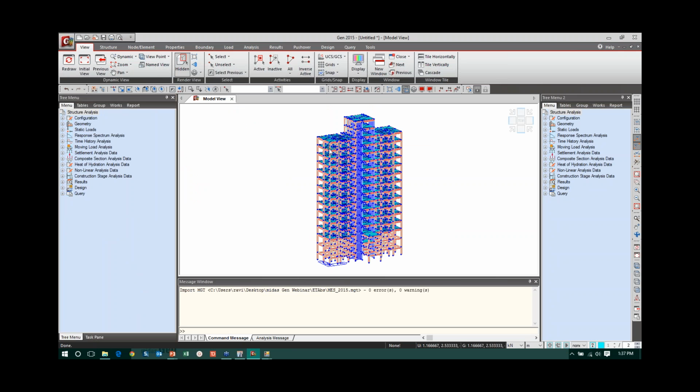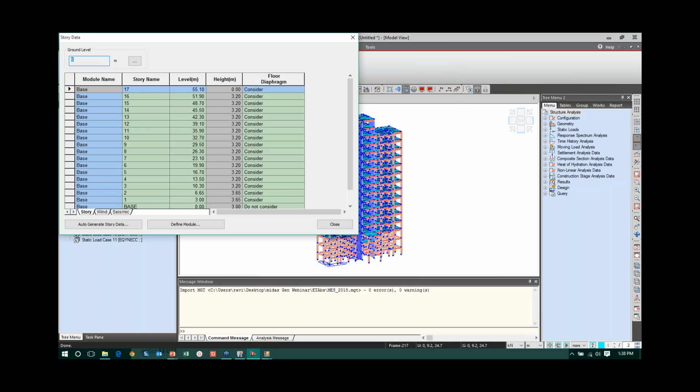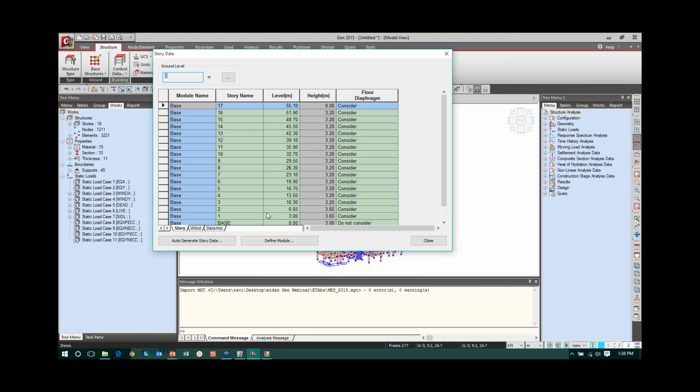Yeah, here you can see the complete model is there. Here you also get the geometry, the plate thickness and everything, and all your gravity loads like pressure loads, element beam loads, nodal loads, all the loads will also be imported. And also the story definitions and the story names and everything are automatically taken from ETABS. So there is no need to define the stories and all the boundaries.